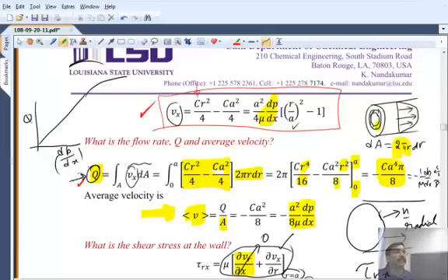In practice, as I said, it's the instability that causes it to lose its realizability, meaning you cannot realize it in an experiment. But people have done experiments in recent years, in the last 10, 15 years or so, in extremely carefully controlled pipe flow. You have to make sure that the vibrations from the pump don't vibrate the pipe even by a micron. So very high precision control. Then you can achieve this velocity profile up to a Reynolds number of 100,000. People then measure the velocity profile at 100,000 to make sure that it agrees with this. Okay?